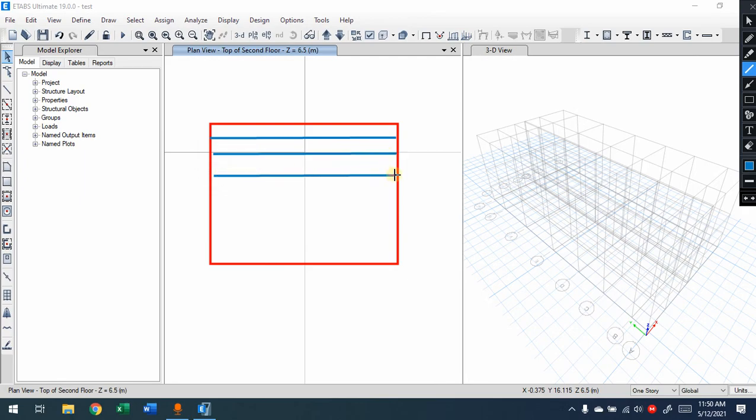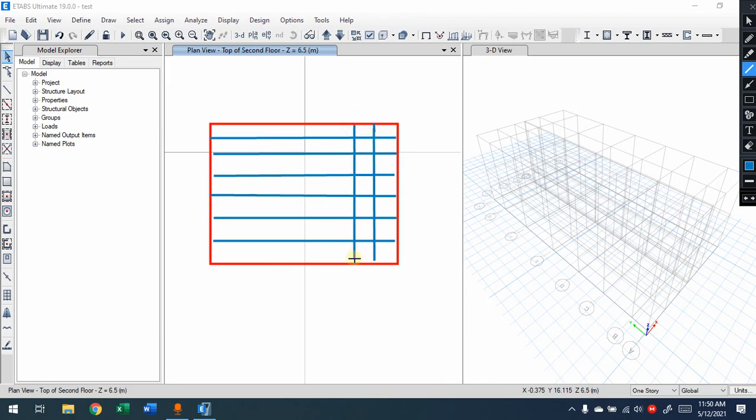So this is how the design of slab will be done in ETABS. You will decide the mesh size. They call it the mesh here. This is the way that the finite element method works: you divide the element that you have into smaller portions and use numerical methods for analysis. So each of those small portions will be considered a small slab.